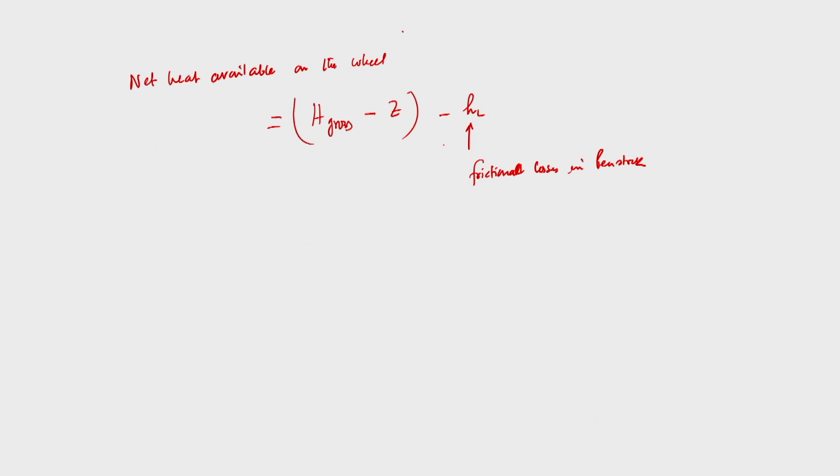Now, we need to quantify the power. Whenever fluid is flowing through the nozzle, the head gives us velocity, so kinetic energy. The power output from the nozzle may not be the power transferred by the fluid to the wheel. There will be a certain amount of losses, and we need to know what they are. Before we discuss the losses, let us first analyze the efficiency, and to do that we need to draw the velocity triangles at the inlet and outlet.